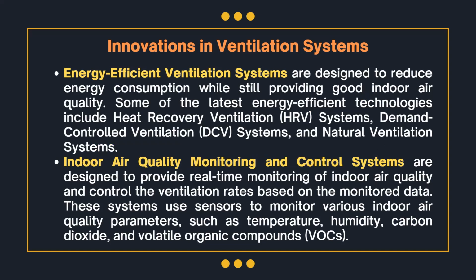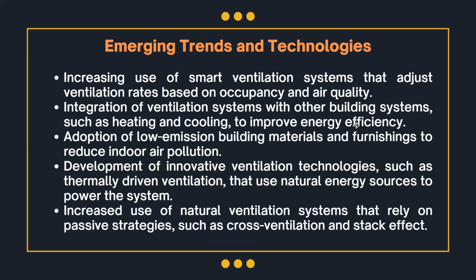High energy efficient ventilation systems, which are designed to reduce energy consumption while still providing good indoor air quality. Some of the latest energy efficient technologies include heat recovery ventilation HRV systems, demand control ventilation DCV systems, and natural ventilation systems. Indoor air quality monitoring and control systems, which are designed to provide real time monitoring of indoor air quality and control the ventilation rates based on the monitored data. These systems use sensors to monitor various indoor air quality parameters such as temperature, humidity, carbon dioxide, and volatile organic compounds.